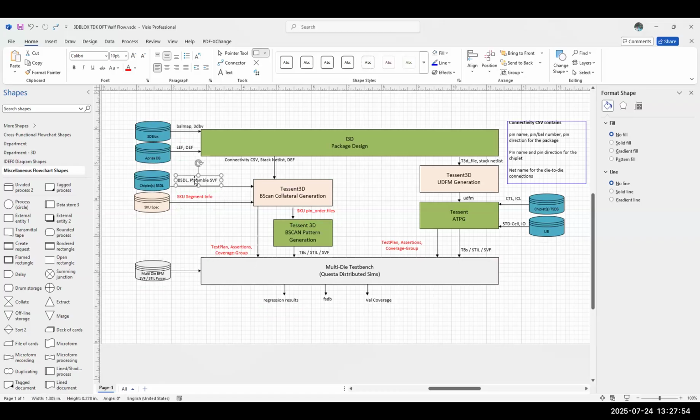At least for a 2.5D, you have a handful of pins, and you can test that entire chip by running patterns through that JTAG interface. In standalone chips, you can multiplex the SerDes and have access to all those IOs, but that's not really a luxury we can do unless those pins are going out.